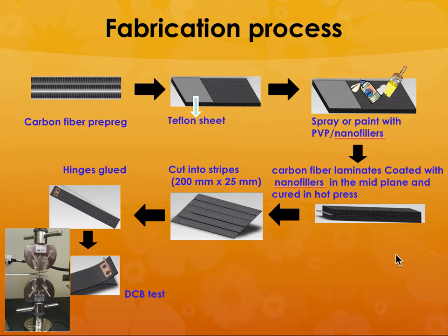So how do we know whether or not our composite material is going to benefit as a result of this? So you put that between the layers, and you put a crack initiating layer, and after you apply this nanoparticle between the layers, you want to see how easy or difficult it is for you to separate those layers. That will tell you whether or not you are improving the interlaminar toughness of your composite material. So this is called the double cantilever beam testing in composite materials. So that's a standard ASTM test that you would use for measuring the effect of these nano additives.